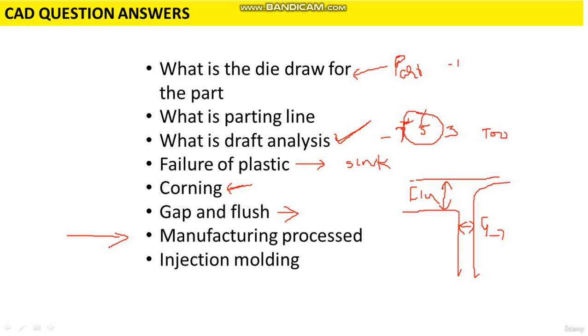That is very common, the 99% we use is injection molding. So in injection molding, what is the core side, where should the A surface be, core or cavity, and which one is movable, core or cavity? They may ask. Generally, suppose this is your machine for injection molding, and there will be a cavity and there will be a core.